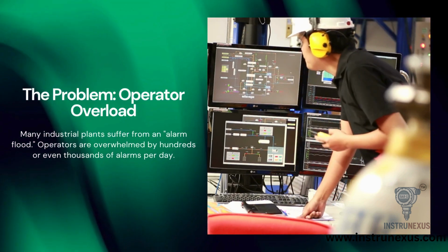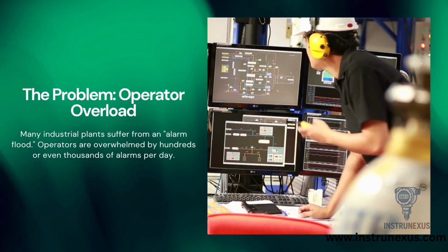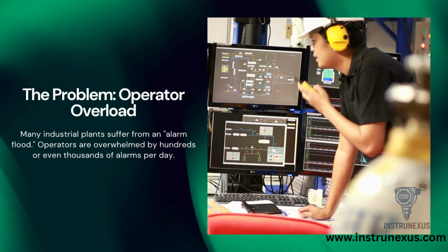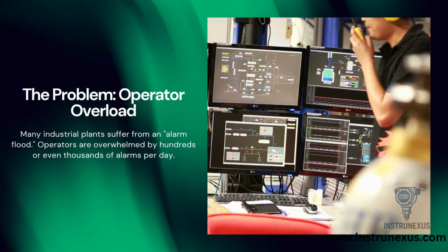When everything is an alarm, nothing is an alarm. This sensory overload leads to desensitization, where operators simply stop hearing the chimes, or worse, acknowledge them without looking just to make the noise stop. This is a recipe for disaster.